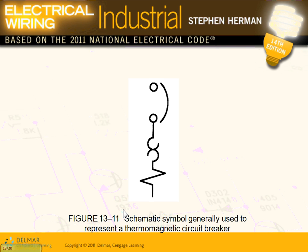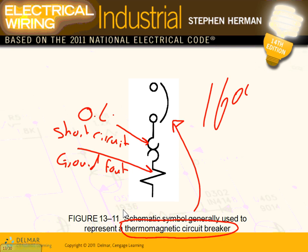This is the one that you guys love all the time. You're going to live and die with it. It's called the thermomagnetic circuit breaker. That's the one that we deal with all the time. We don't show this when we draw; we just draw a circuit breaker. This component is the overload component, and this component is short circuit and ground fault. These are your thermomagnetic circuit breakers. You can buy them probably up to 1600 amps. After that, it becomes electronic circuit breakers.